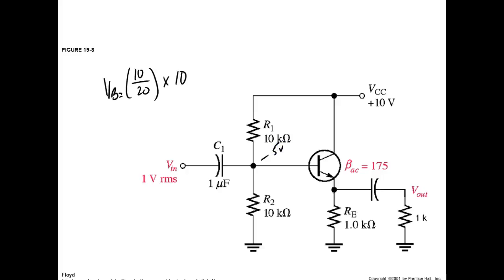Normally, you know that's 1/2, right? Everybody okay? Of course, we knew that without even putting the formula up there, because we've got 2 resistors that are the same size, right? You understand that? Okay. So what would be right here? 4.3 volts, right?